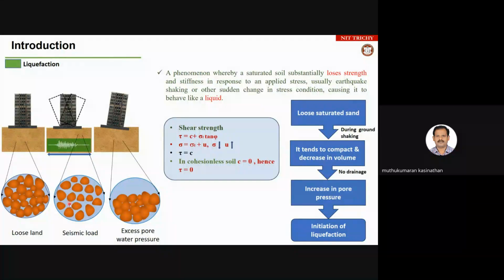If the pore pressure development is more than the effective stress of the soil, the soil becomes loosened and will act as a single body. Then it will float in the water. So the shear strength of the soil is completely lost. This is the concept of liquefaction. Once that has happened, whatever loading you have on top of the soil simply goes down, leading to severe structural damage or serviceability problems.